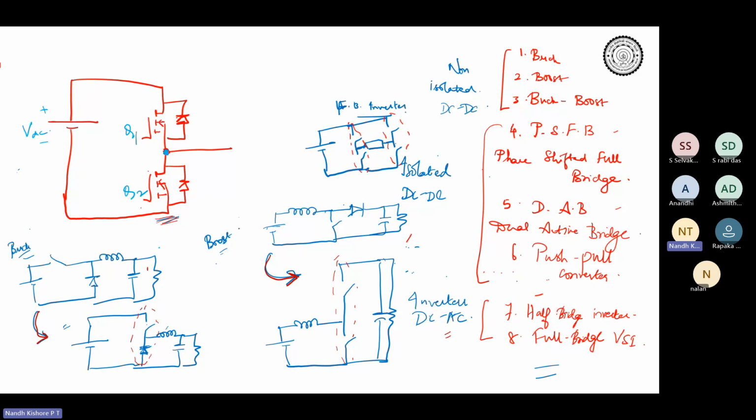If you observe some switching behavior of the device in a half bridge circuit, you can fairly estimate that the device might behave in the same way if it is used in a buck converter or a boost converter or an inverter and so on. Since the half bridge is the core of almost all the converters, the devices are characterized in a half bridge configuration. Fine, so I hope this is clear now.